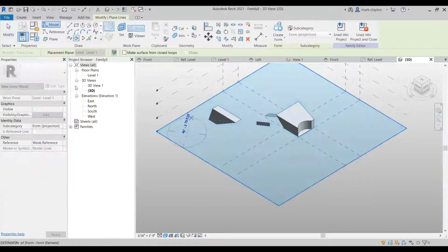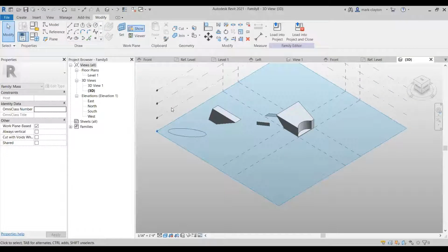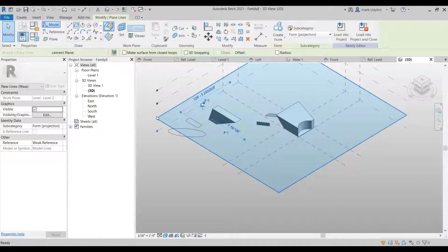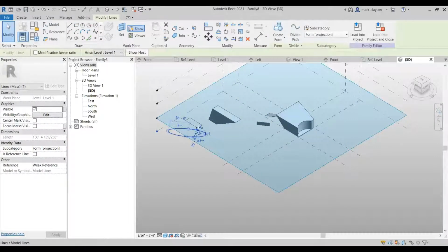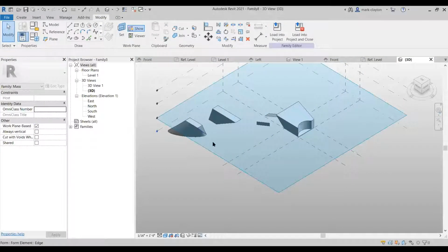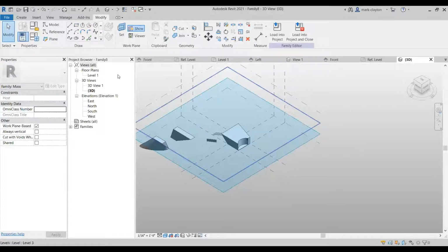So, you can do much more complicated blends. So let's take an ellipse and go up to another level and put a rectangle. And then pick those two, create form, and I got this weird thing that deforms from an ellipse to a rectangle. Now that was just two elements, a top profile and a bottom profile. But you can also have intermediate profiles.